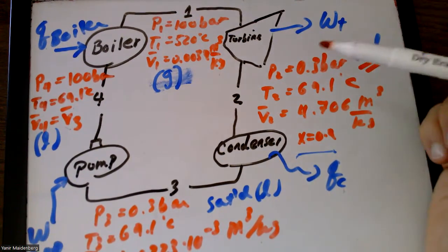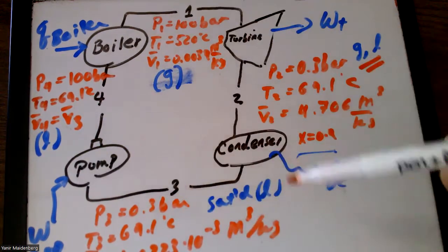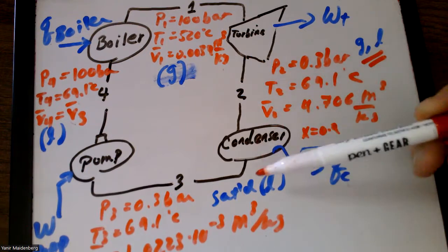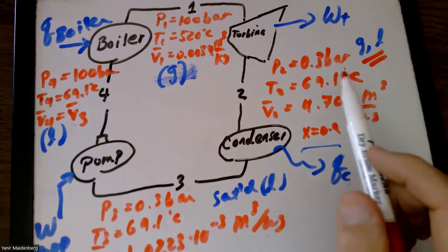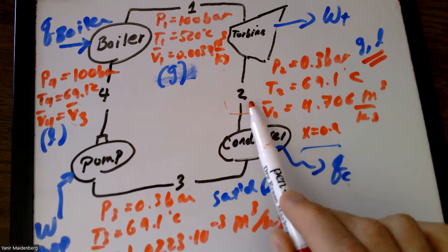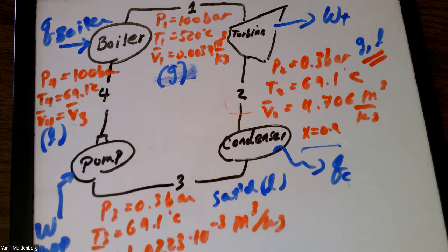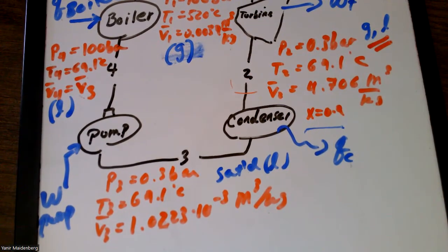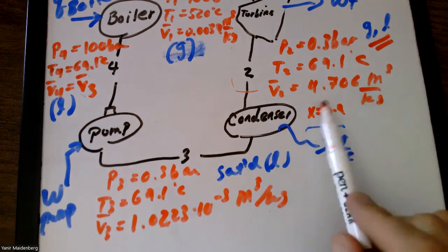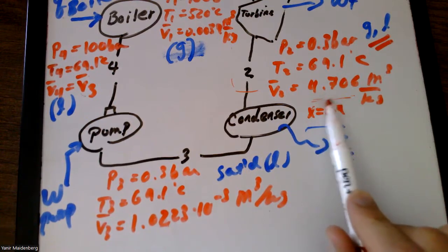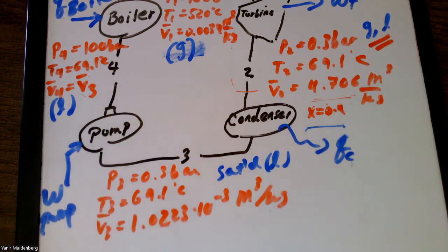Okay, and the idea for a cycle is to repeat. So what you're going to do now is prepare it, you're going to recover it. Well, you can treat stream 2 directly to go to stream 1. The problem is that stream 2 has got some gas in it. And why is that a problem? Because gas takes up a lot of space, and this is a lot of space. So you don't want to handle that. You don't want to have to deal with this for three different iterations through the condenser, the pump, the boiler.